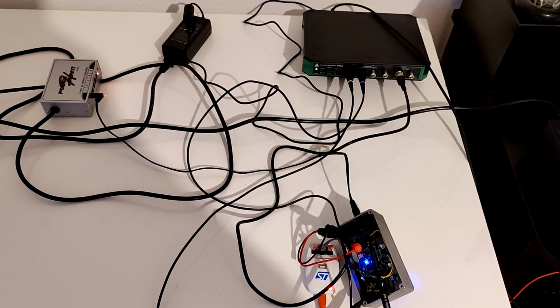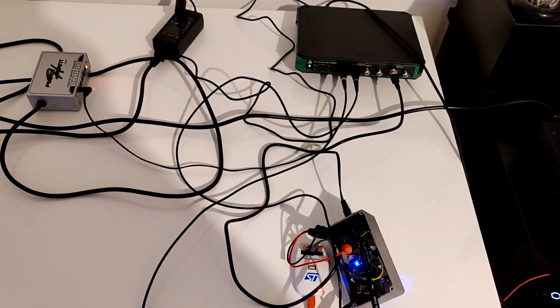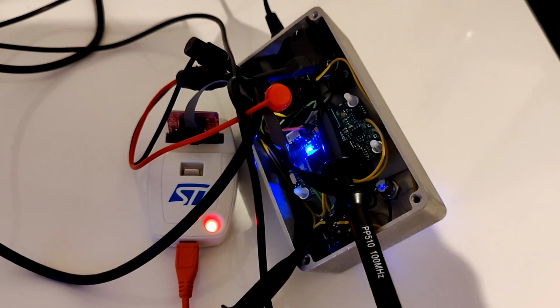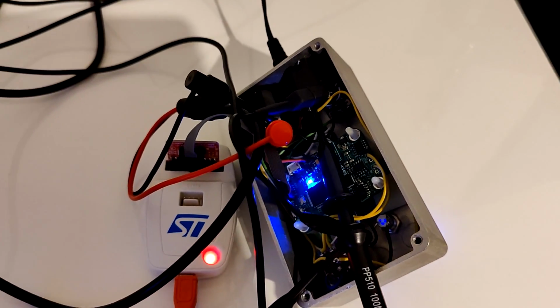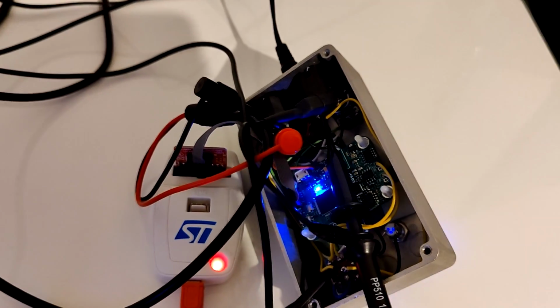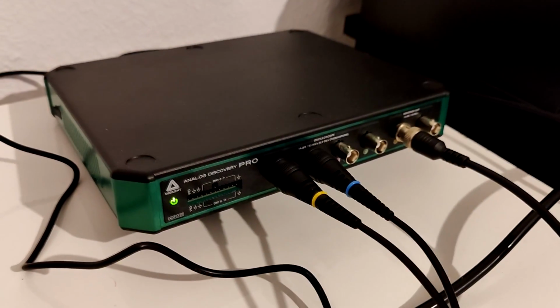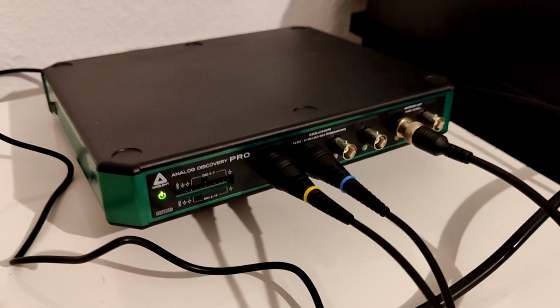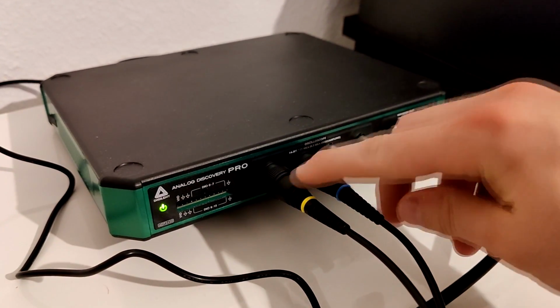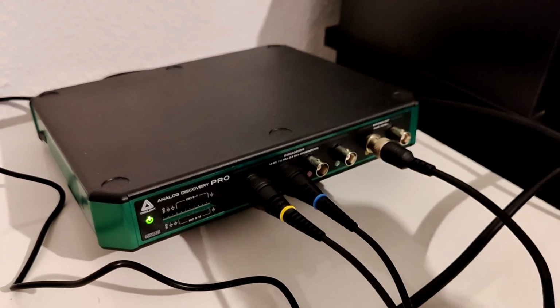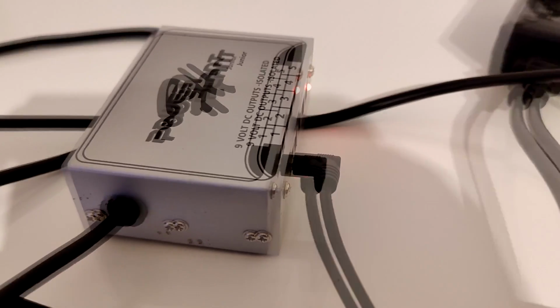So let's take a quick look at the hardware we're using to test and then play through this noise gate effect. Down here, as usual, we have the guitar DSP already running. I've probed it up with some probes, input and output, also with a wave generator at the signal input. I'm using an ST-Link V2 for debugging and programming, and these probes then hook up to the Digilent Analog Discovery Pro. One is probing the input to this effects unit and one is probing the output, and I also have one of these wave gen outputs connected up to my input, so I can do some Bode plots and so forth. This system is then powered via this very simple 9-volt guitar power supply, and that's pretty much it.